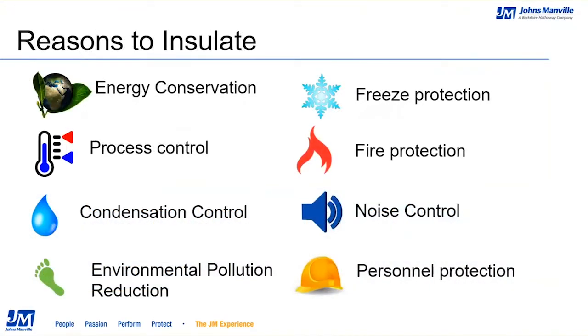Reasons to insulate. Why do we insulate? The main reason we insulate is energy conservation. Insulation limits heat loss or gain within a system. Systems will perform more efficiently if they can maintain the desired outputs with less demand. This helps provide process control.